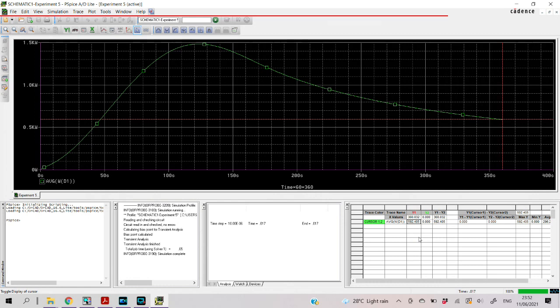So we tried to measure the power across this RC load. Using the PSPICE simulation, we are able to measure the peak current, the angle of delay, or the angle of conduction for the circuit, and the average values like the average current, average power, and its RMS values.